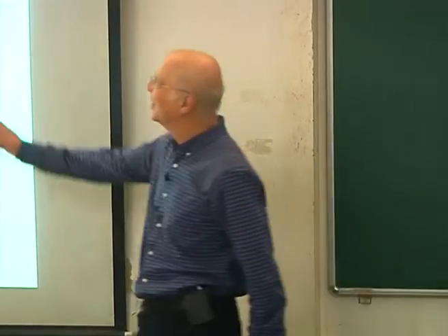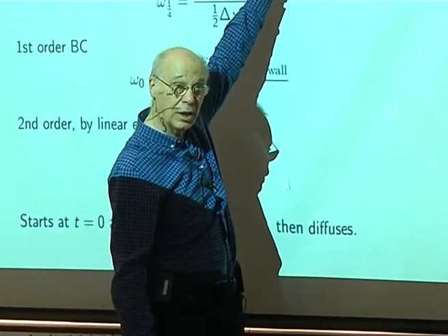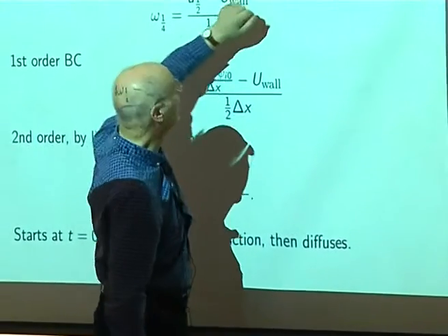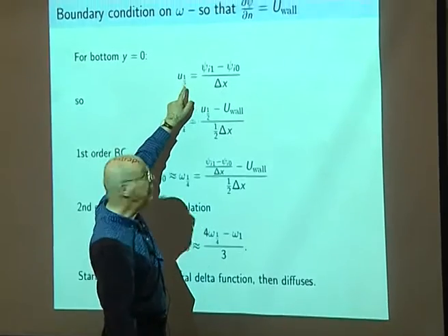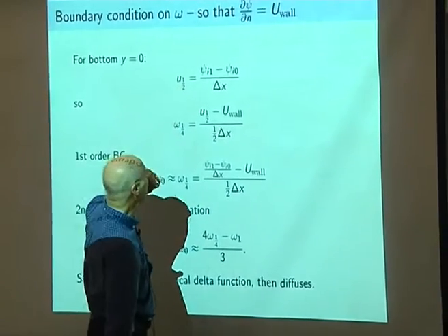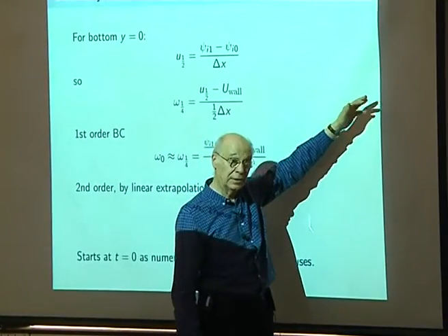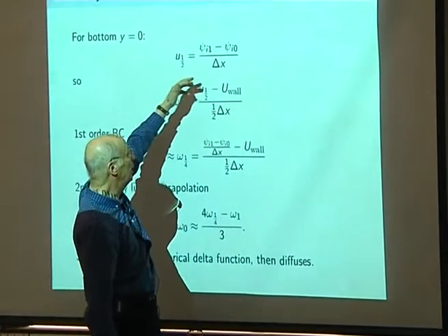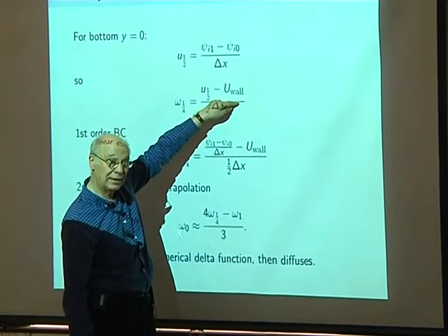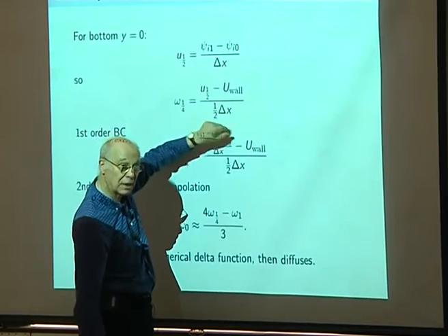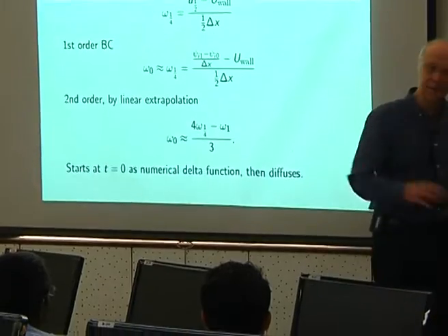I can estimate the tangential velocity, which is given by d psi by dy. So this is a delta y. And from 0 to 1 central differencing, so second order accurately, I get it at the point half. And then the vorticity, when dv by dx is 0 because v is 0, is equal to du by dy. And then so a quarter in and 0 in, and I have to divide by the distance between them, half delta x, I get it at the quarter point, which isn't quite the boundary, and therefore we do the linear.